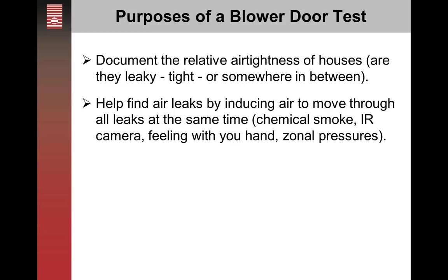fixed or not? It also is used to help find those air leaks by inducing air to move through the house, which can then be found through the use of chemical smoke, an infrared camera, even feeling around locations where you think there might be airflow and just feeling with your hand. And then a more advanced method would be using zonal pressure diagnostics to help find those locations and which ones are the primary ones to start working on.